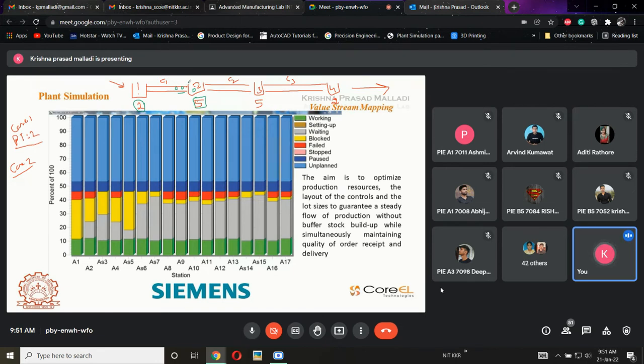Now, okay, this operation was done. After 5 minutes, this part will enter the third machine. Similarly, there will be continuous preparation of material. Why? Because this processing time is 2. Now between these two stations there won't be any blockage. Why? Because every 2 minutes a part will be produced and given to this one. And every 5 minutes, whenever this machine is done, a part will enter here.